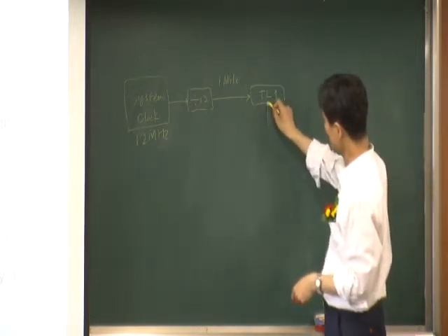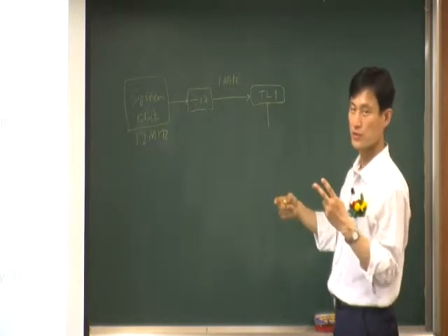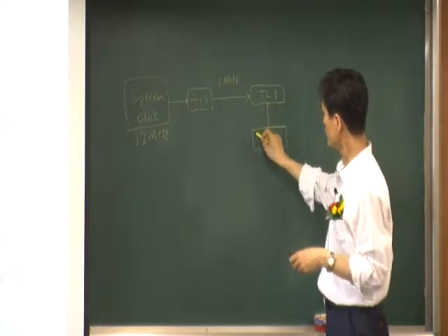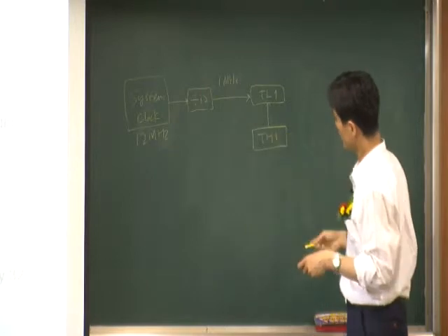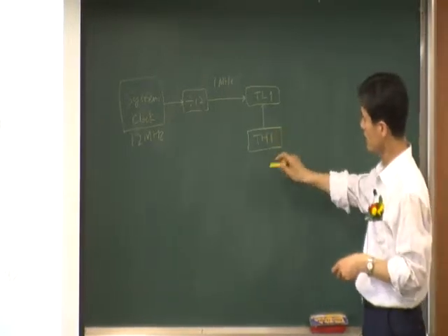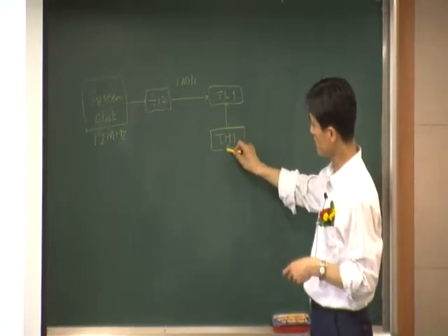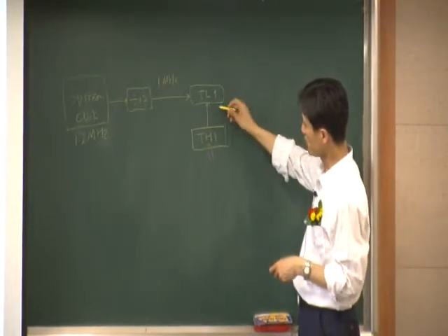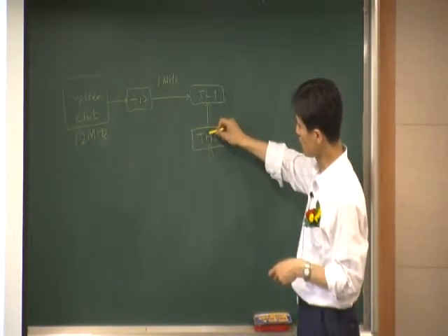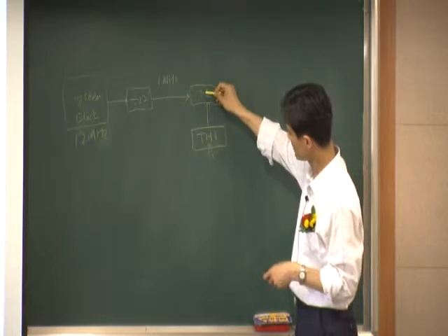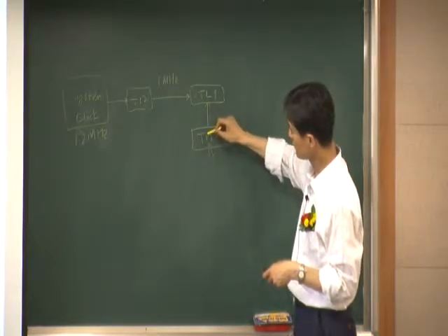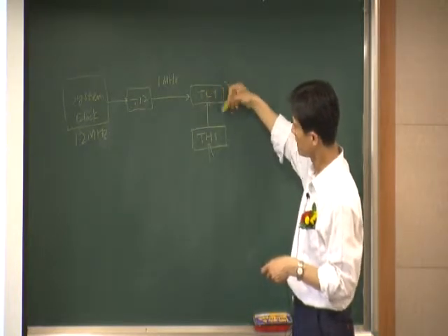And now, when you run the timer with mode 2, mode 2 has an auto reload feature. What that means is the initial value, you want to program it here. Then whenever this timer runs, this initial value will be auto reloaded into here, okay? That initial value is copied into here, and then it runs.